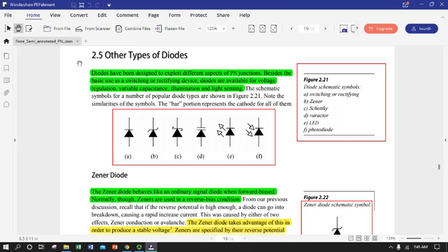We defined the p-n junction as a physical area where p-type and n-type semiconducting materials meet, and the majority charge carriers from both annihilate, and we get a little layer of intrinsic semiconducting material that forms an energy hill that we have to overcome with an applied voltage to get the semiconductor junction to conduct, and that it only conducts in one direction. So we formed a diode, or a one-way conductor.